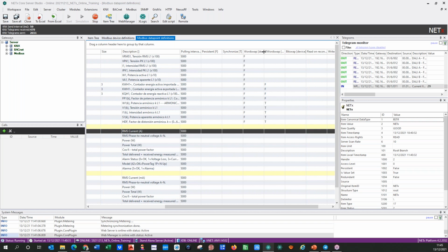The double word swap, you can see here, is by default in the device configuration, but here you can change it specifically for each of these registers. Sometimes you have to put it again in false, and the double word swap if it is the double register, the 32 bits register, again, but some not. Some you have to put in true or do nothing.